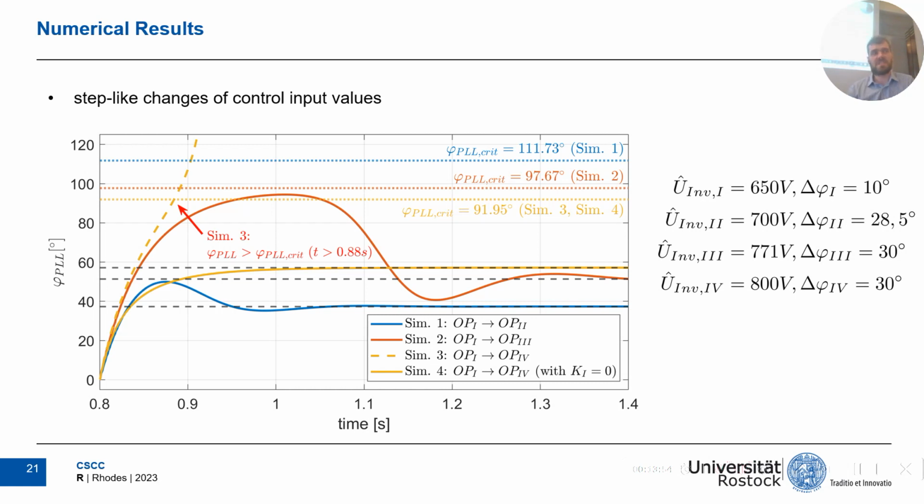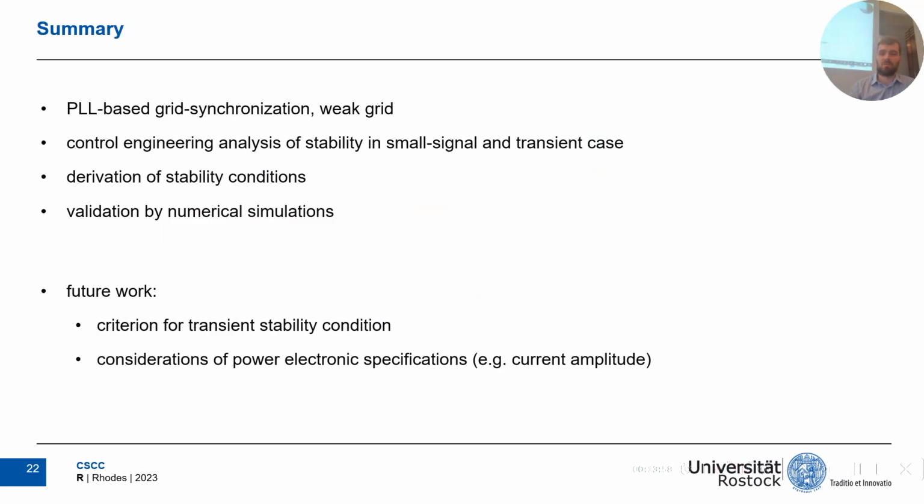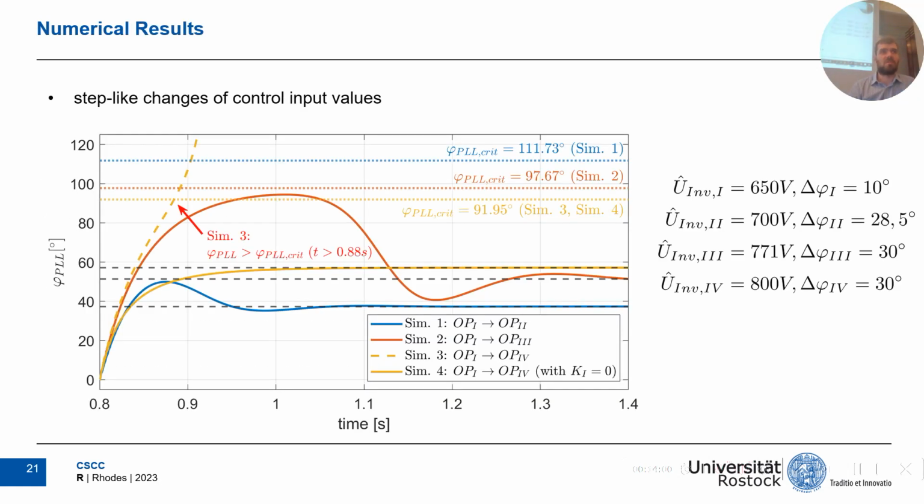This is just an extreme example, which comes with, of course, more difficulties, but just to show you that by retuning the PLL, we can decrease the overshoot. In this case, decrease the overshoot to 0, which means that we will not hit the critical value, and we can reach the stable operating point 2.